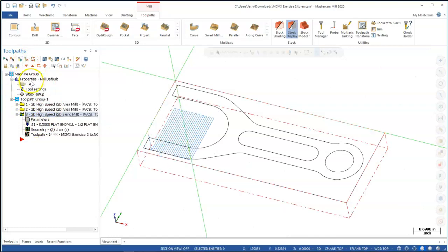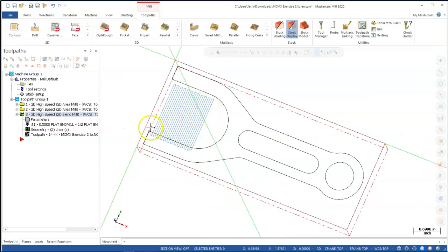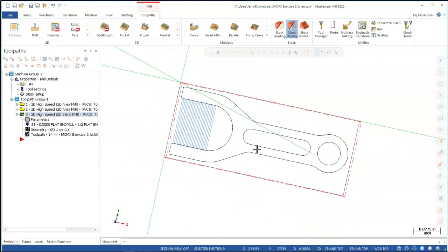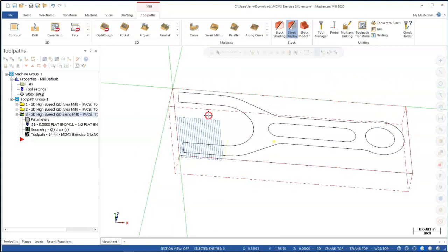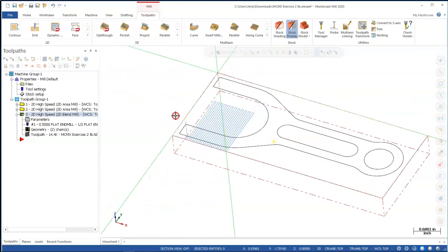All right, let's give it one more. All right, so again, it's just going between the lines, and this is more like the traditional lace. And let's take a look, because I think it is also going to blow out my material. All right, notice the lines are going, so being able to read and identify those toolpaths, in that kind of isometric rotated view, it's not as apparent.